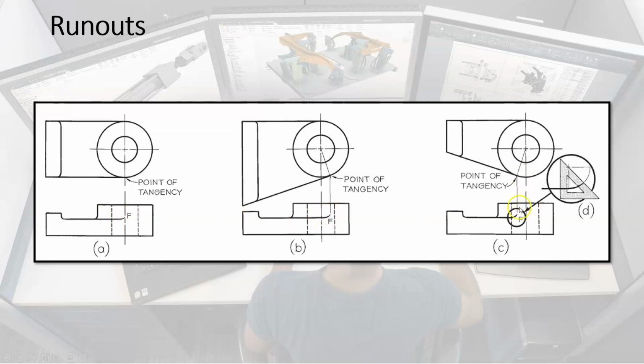How do we construct that runout? Well, we construct it like this. We draw a quarter circle here, and then we trim it off so that it's basically 1/8 of a circle. We trim it off at 45 degrees. When we are doing this in AutoCAD, I will show you how to do this construction. Okay, so don't worry. I'll show you. There's some tricks that I want to show you. So I'll be able to show you when and if we're doing drawings with this. I think there are some, but don't hold me to that.